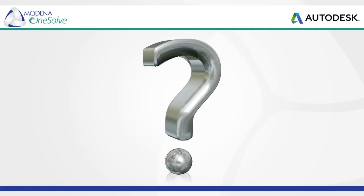In terms of working on these files in BIM 360, we got a question that came through. Will we see updates? Because the data is being downloaded or synchronized between offline and online, when a file is checked out to work on it, nobody else will be able to edit that file in that time. And whenever we check that information back into BIM 360 Design, all those changes that were made are then synchronized to the project, which will then make those available to the rest of the team.